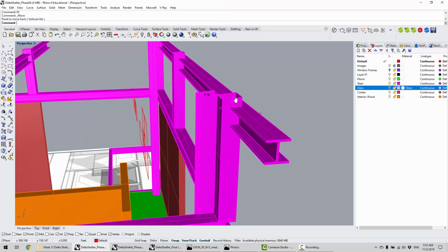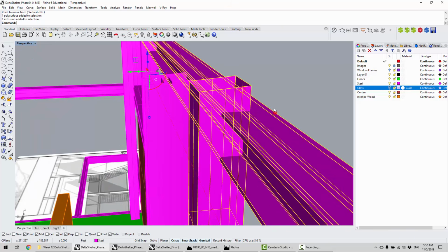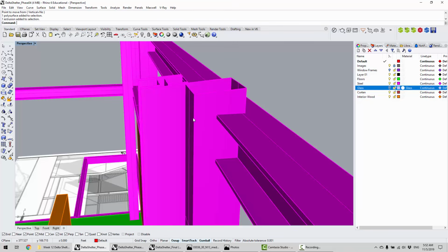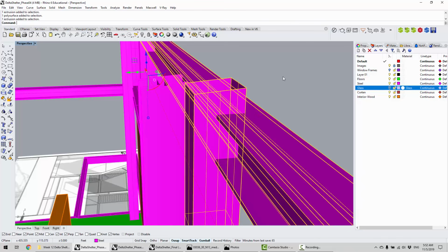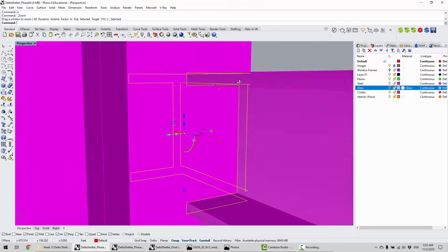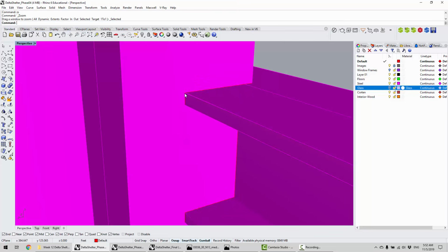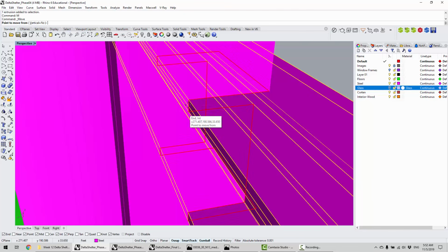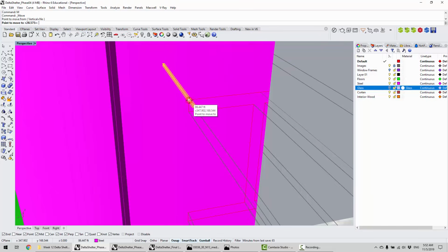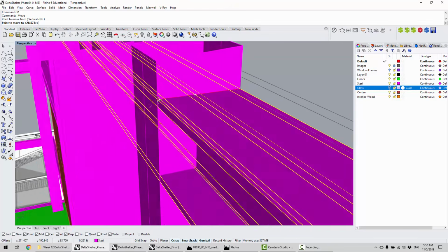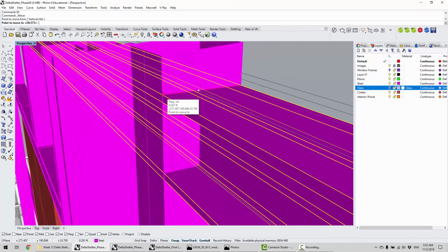So this is how I do it. In this case, I want to move this face to here. You select these guys, you run an intersect, which will give you their joint intersection. But what it really gives me is a curve point to snap to. So when I move, I can use that curve point, and then using my object tracks, it will snap to the perpendicular point on that face or surface.